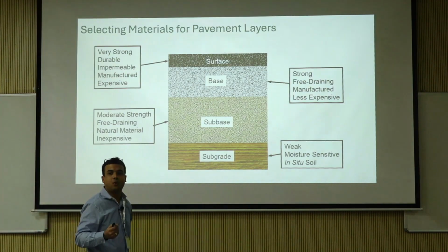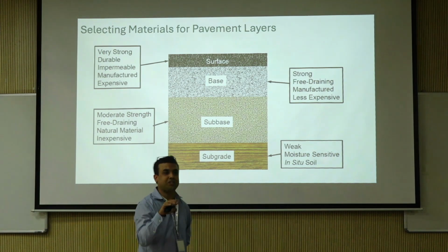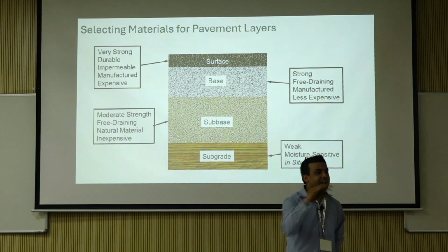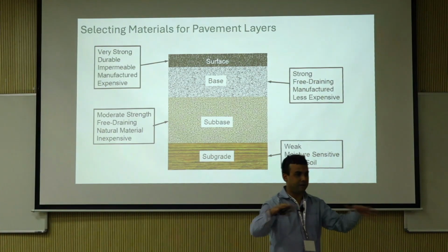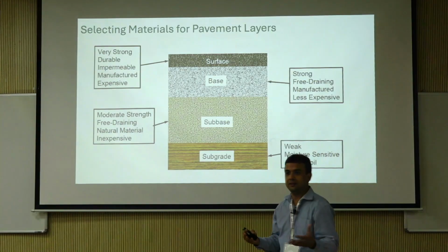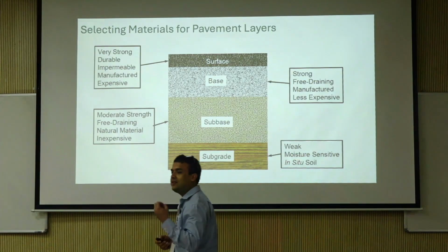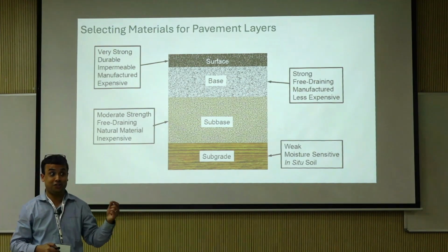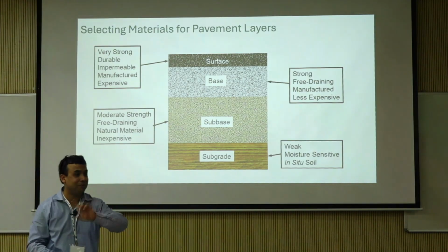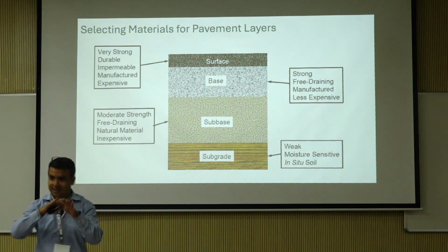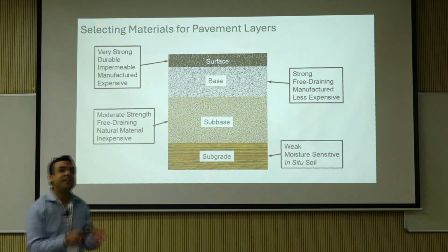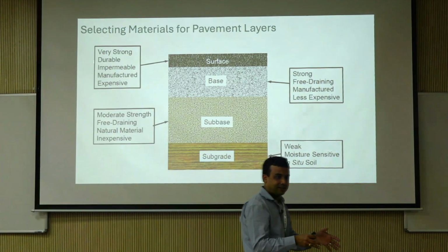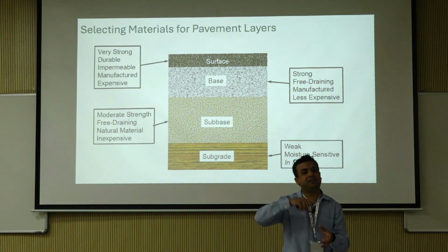Let's talk about railroads. Some people asked questions about railroads in their homework 0. You know what a ballast layer is? The rock layer. That's called ballast, right? Do you know what is the primary function of a ballast layer? Drainage. It's not load transfer. I mean, it does transfer load, but the primary requirement for selection of a material is drainage. Because if water doesn't drain, what happens?